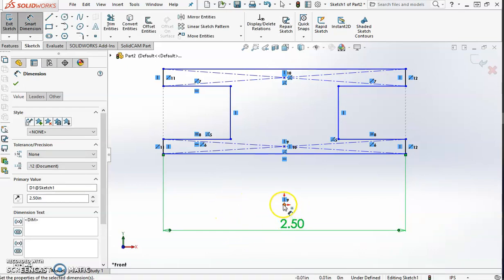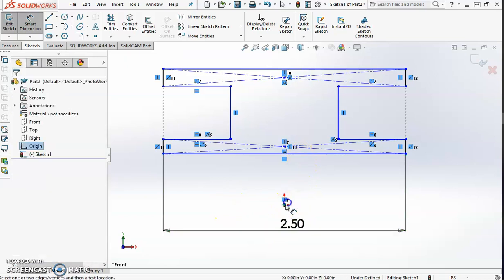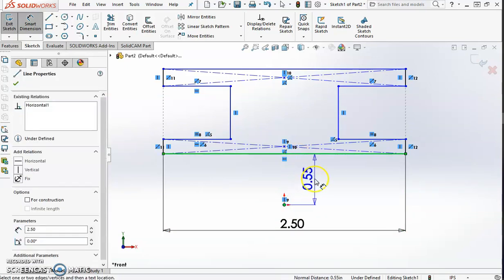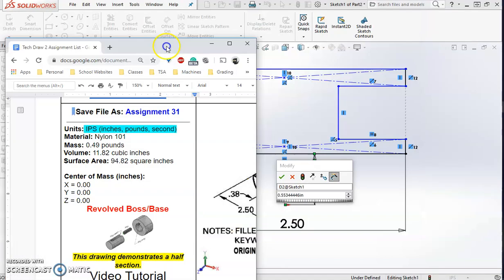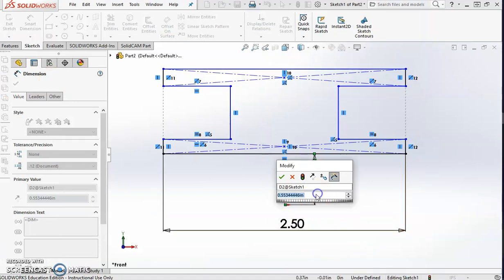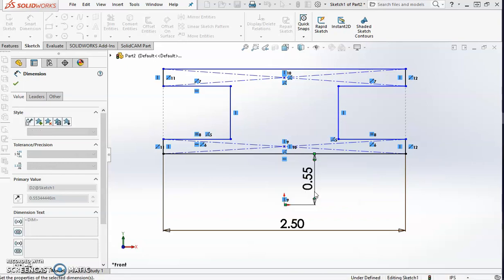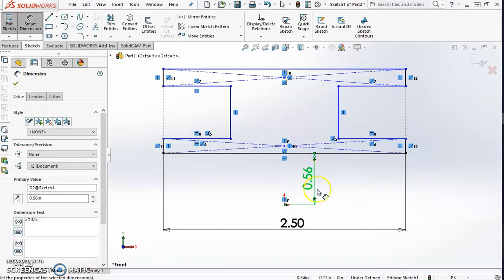And my spacing from my origin away, so from my origin to this bottom line here, is going to be your first diameter, so that's that 1.12 divided by 2. So we're actually going from here to here, not from there all the way down to the bottom of the circle. So 1.12 divided by 2. And if I'm talking about dividing numbers, it's these numbers again here, these diameters that I'm going to be using. So just look back at that picture. So you could simply just type in 1.12/2. So that is going to be 0.56.